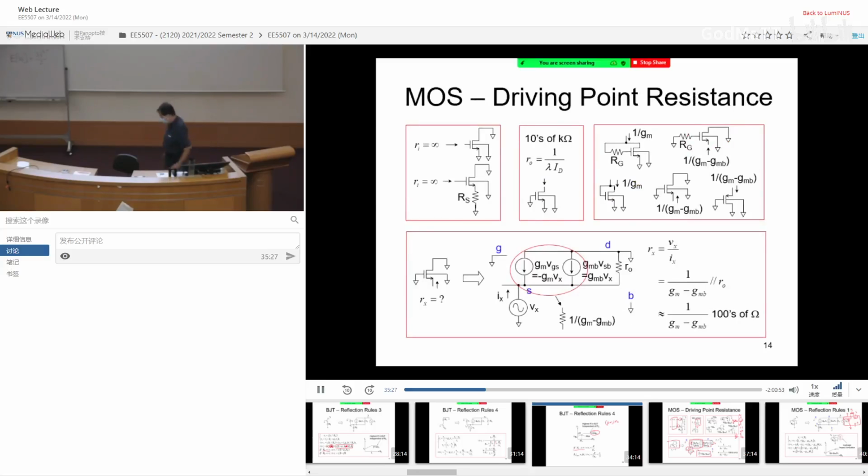Okay, we're done with MOSFET. We're done with BJT. Now, MOSFET is actually quite similar to BJT cases. So, first thing, the gate is infinite. Very simple. Look into the gate. It should give you open circuit, infinite. Looking into the drain terminal, you also know R0, except that this output resistance equation is governed by lambda, not early voltage. So 1 over lambda ID. Okay?